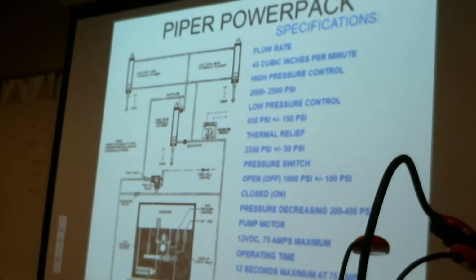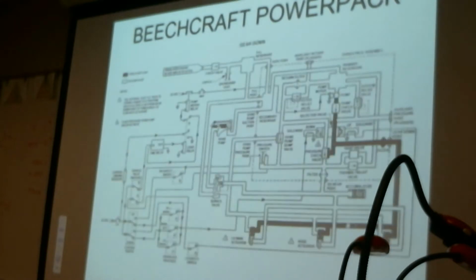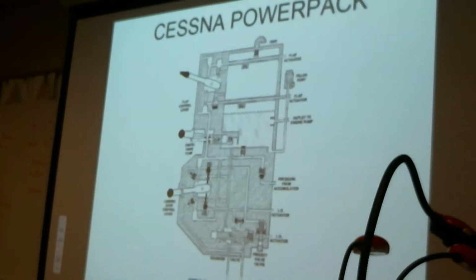Okay. All right, you're up, you're down. What does that dotted box mean again? Power pack. That's right. Okay. This is Cessna's idea of what they call a power pack. And again, for some Cessnas, what they've got is an integral reservoir and selector valves that they use for powering flaps and landing gear extension and retraction, and also an emergency hand pump for extension of gear.